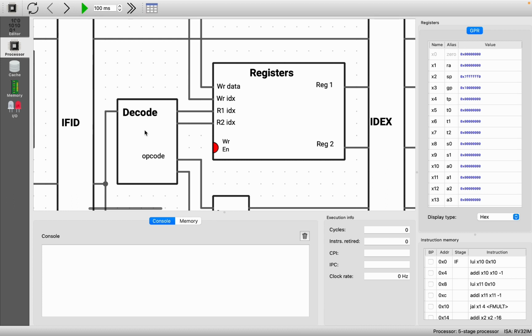So, the central idea behind any RISC architecture, and that of course includes RISC-V, is that instead of dedicating hardware to decoding your instructions, you make all of the instructions simpler so that you have to do as little logic as possible to decode them. And then you can use the extra area that you were using to make your complicated decoder for stuff that actually improves performance significantly. Like you might invest in a more accurate branch predictor, for example, or more cache.